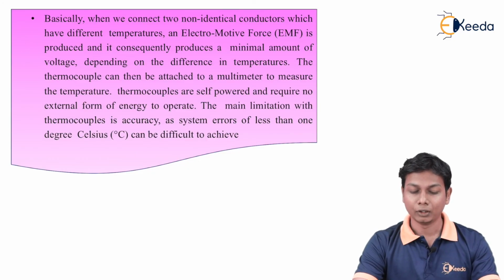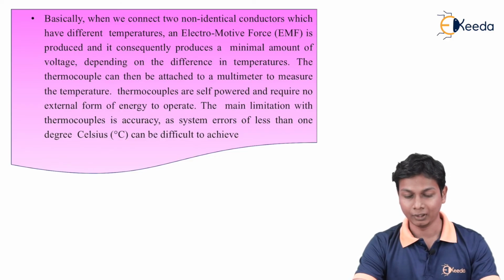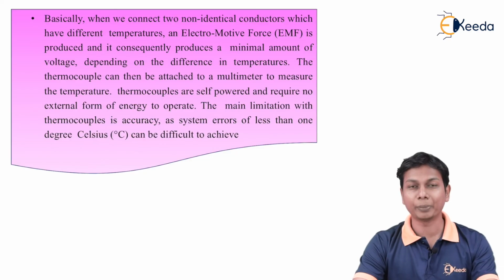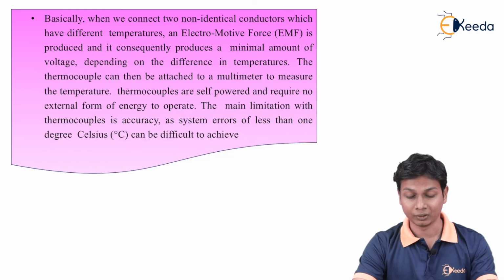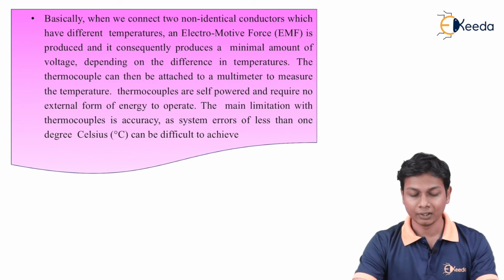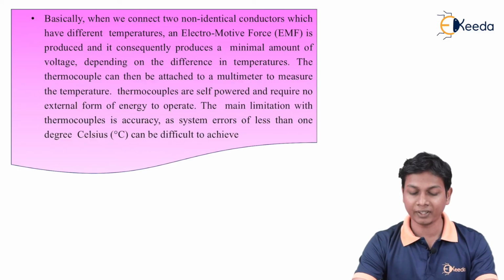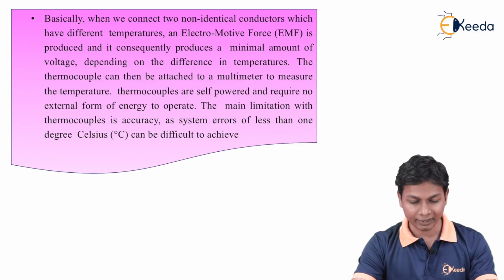Basically, we connect two different conductors which are at different temperatures. An electromotive force, that is EMF, is constantly produced, a minimal amount of voltage depending on the difference in temperature, and the thermocouple can then be attached to a multimeter to measure the temperature.